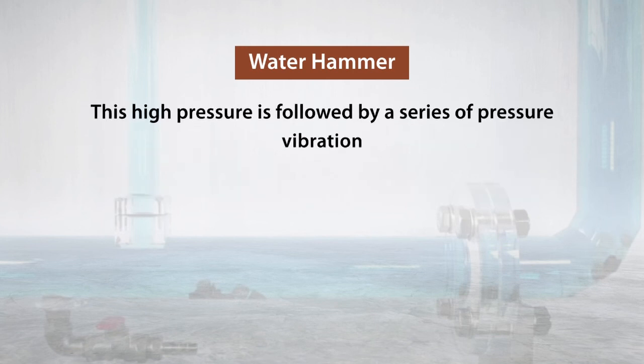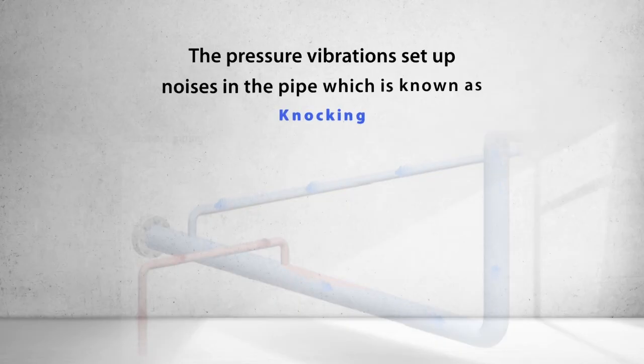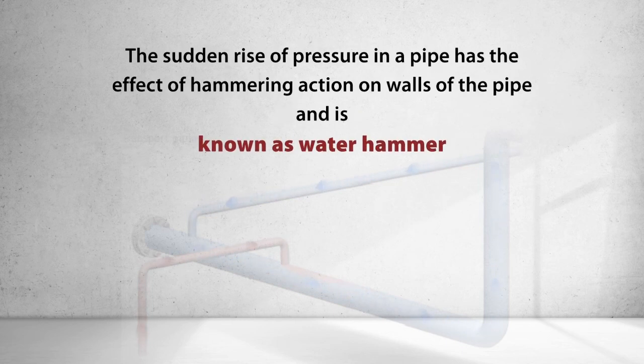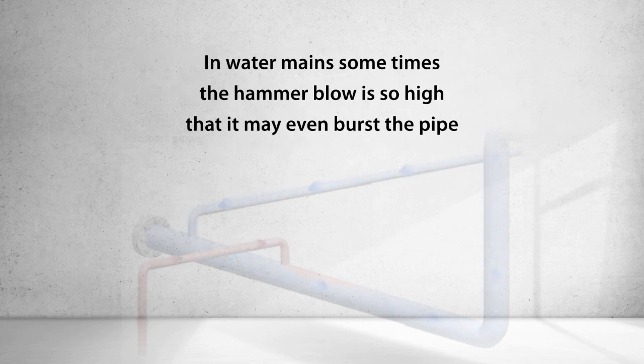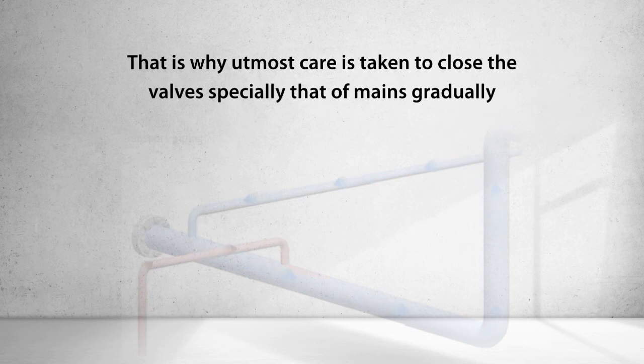This high pressure is followed by a series of pressure vibrations. The pressure vibrations set up noises in the pipe, which is known as knocking. The sudden rise of pressure in a pipe has the effect of hammering action on the walls of the pipe and is known as the water hammer. In water mains, sometimes the hammer blow is so high that it may even burst the pipe. That is why utmost care is taken to close the valves, especially those of mains, gradually.